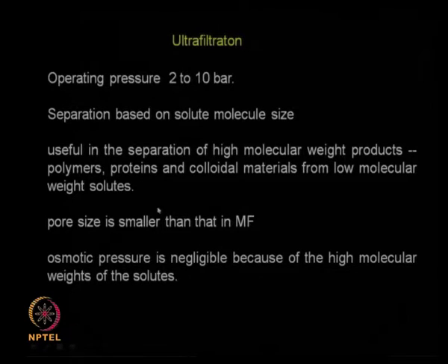Here the pore size is much smaller than in microfiltration, much smaller, that is why you are resorting to higher pressure. Okay. So when the pore size is very small, you have to go for higher pressure. Here osmotic pressure is also negligible because of the higher molecular weight of the solutes, that is what we are dealing with actually.